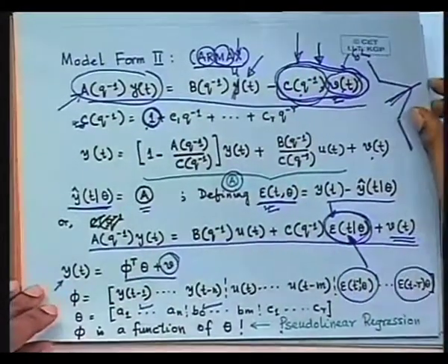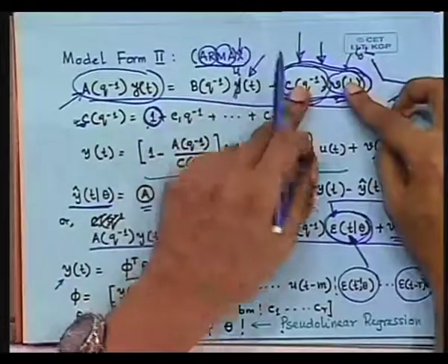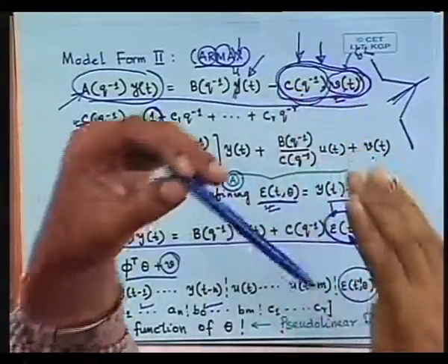Okay. In the ARX model also we had V, but we did not have a moving average of V. There we assumed that the input is only a white noise process. Now we are considering an average of white noise processes. So I am generalizing my autocorrelation assumption. Previously I put a stringent requirement that this V should have a delta-like autocorrelation function. It should be uncorrelated with even the earlier sample. Now I am saying that no, it can be a little correlated with the past 2-3 samples. That is very likely. It is very difficult to get a totally uncorrelated signal.